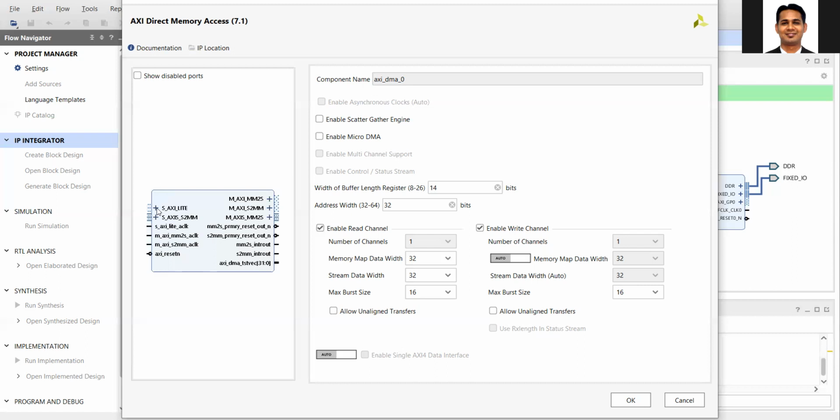Similarly, you need to know whether the DMA transfer is complete or not. So you can again use the AXI Lite to read a particular register in the DMA, and by looking at that register, you can see the current status of the DMA. We will understand this in more detail when we write the C code.